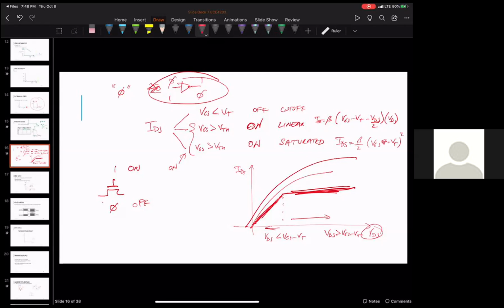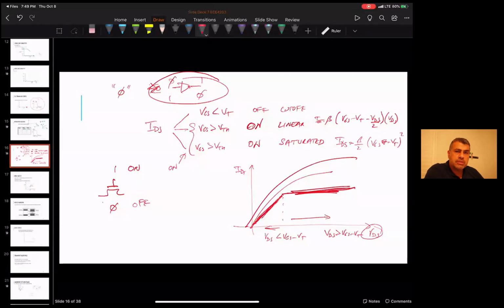Basically, it gets more complex the deeper you look at it. But if you try to design a 54 billion transistor chip, thinking about every single transistor's current versus voltage, it'll take you 54 billion years to get that chip done. So what people do is they design a library of parts using the kind of analysis we're doing now, in simulations and so on, and then use it at a higher level of abstraction as if it was a switch.